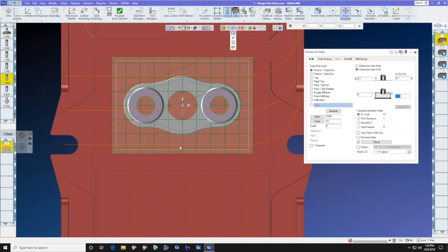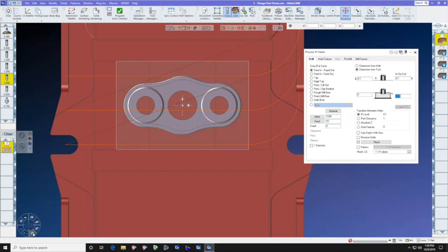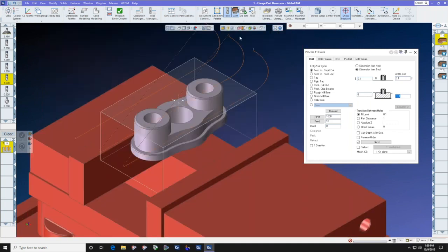In other words, it's broken up at different points during the depth of the part. You can use slice silhouette to find that contiguous profile of the outside of the part and use the silhouette. But we're going to stick with slice plane. And what slice plane does for us, when we turn it on, I can drag it, and you can see it's interactive. It shows me where it is in the part.